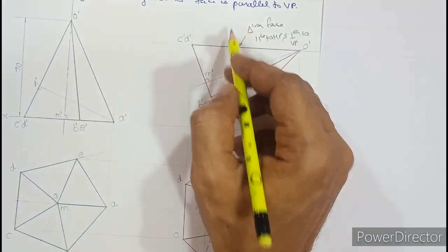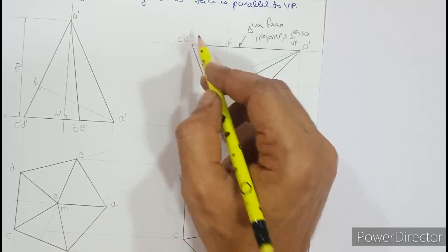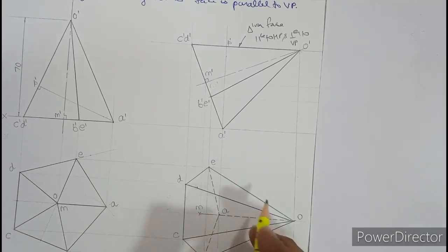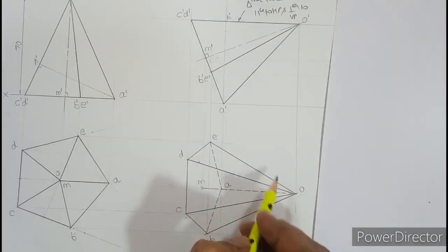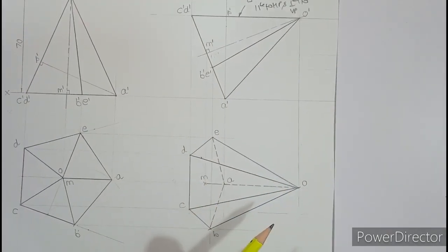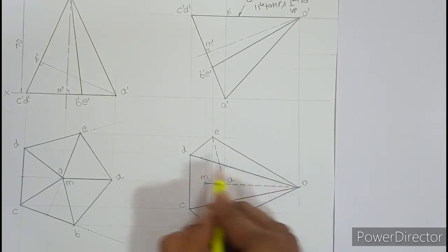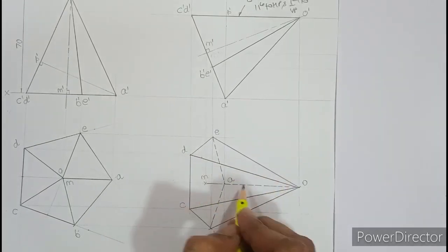Also, if you switch on the bulb, you can see from O to CD everything. The base will not be seen. So base is drawn hidden. The lines which are left out are drawn hidden. As there are 5 slant edges in the pentagonal pyramid, we have drawn only 2. So for the remaining slant edges, we need to understand that from a dotted corner draw a dotted slant edge, and from a dark corner you have to draw a dark slant edge.